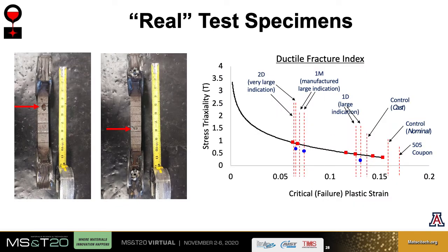These are two tensile specimens with indications that we tested. The leftmost one failed along where the indication was, marked by the red arrow. Interestingly, the second tensile specimen did not fail where the indication was, again marked by the arrow. It failed near the bottom grip.